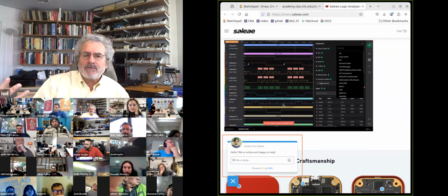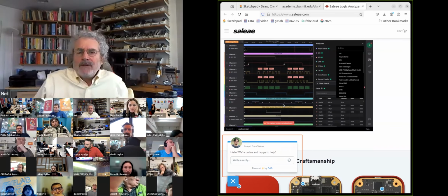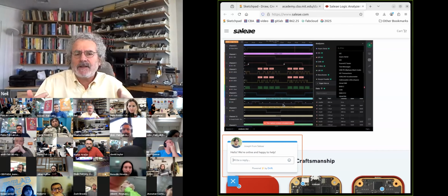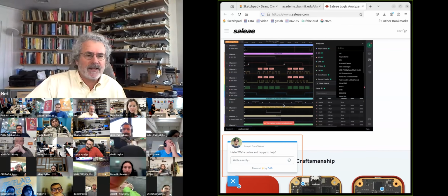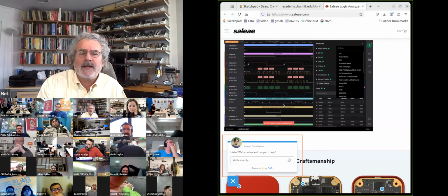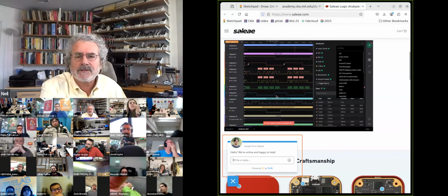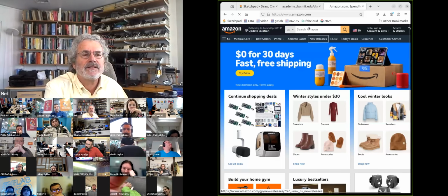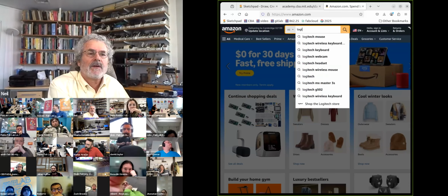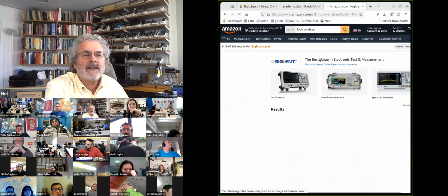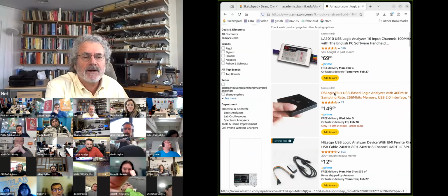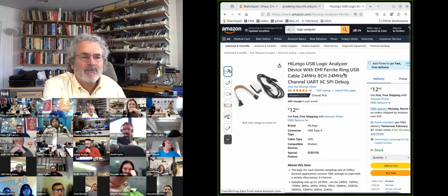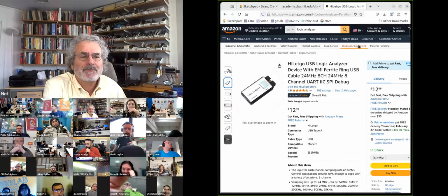I mentioned I2C. When you talk to an I2C device, it may not be working and you may be sending the wrong commands to it. You may misunderstand the commands it's sending back to you. So these logic analyzers are essential to debug that. And again, thanks to our friends in Shenzhen, the Saleae is a few $100s, and you can get these crazy ones for like, here's one for $12, and these work. They're quite usable.